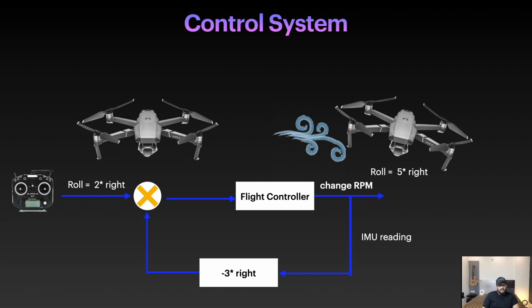And the flight controller checks whether it matches what the user wanted, and if it's not right, then it will generate a compensating signal to the ESC and again change the RPM, and it keeps on going. This will never stop. From the moment you take off to the moment you land, this loop will continue to operate. This feedback loop, this forward path, everything will continue to operate.